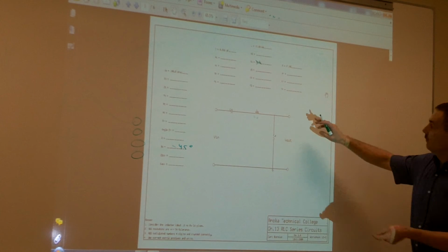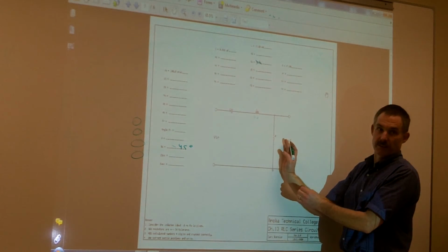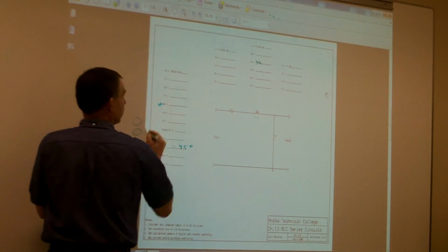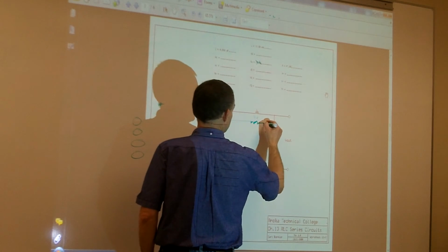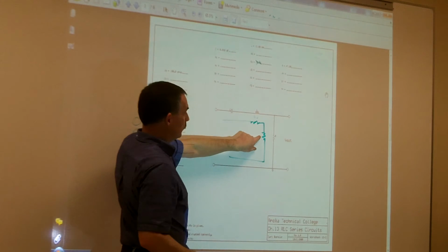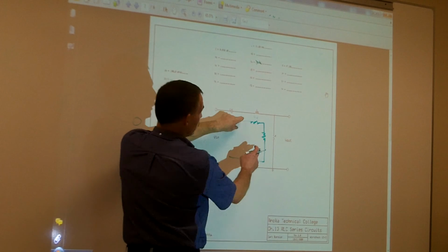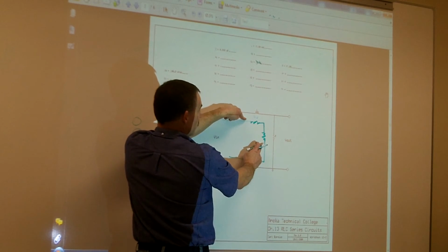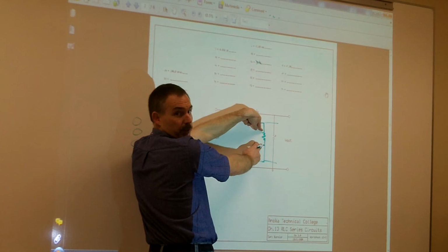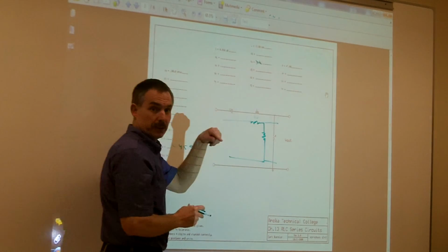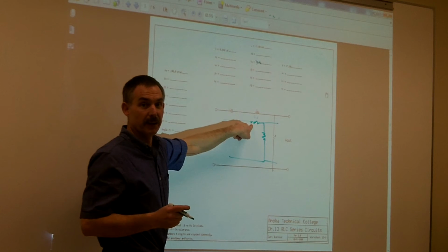Because you take the outputs across your resistor. Right, but remember that the source voltage doesn't see two separate resistors. It only sees the total resistance of the circuit. And so what I actually have is basically a voltage divider. Here's the resistance of the winding, and here's my resistance of my actual resistor. So it's going to just do a voltage drop across those two. Even though the total voltage across that resistance is going to equal my voltage source, since I'm only measuring the voltage across the resistor, I'm only going to get that certain amount of voltage. The remainder is going to drop across the resistance of the winding. Does that make sense?